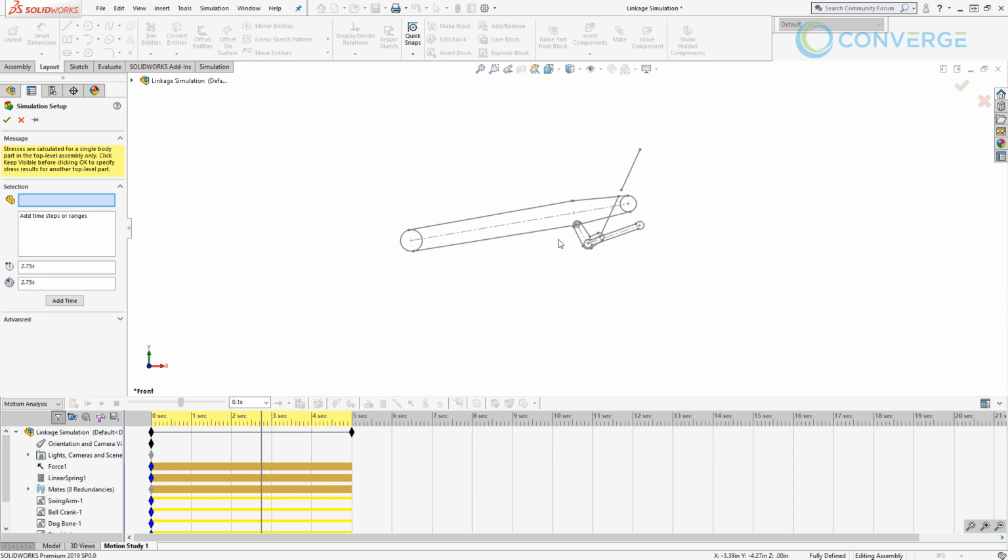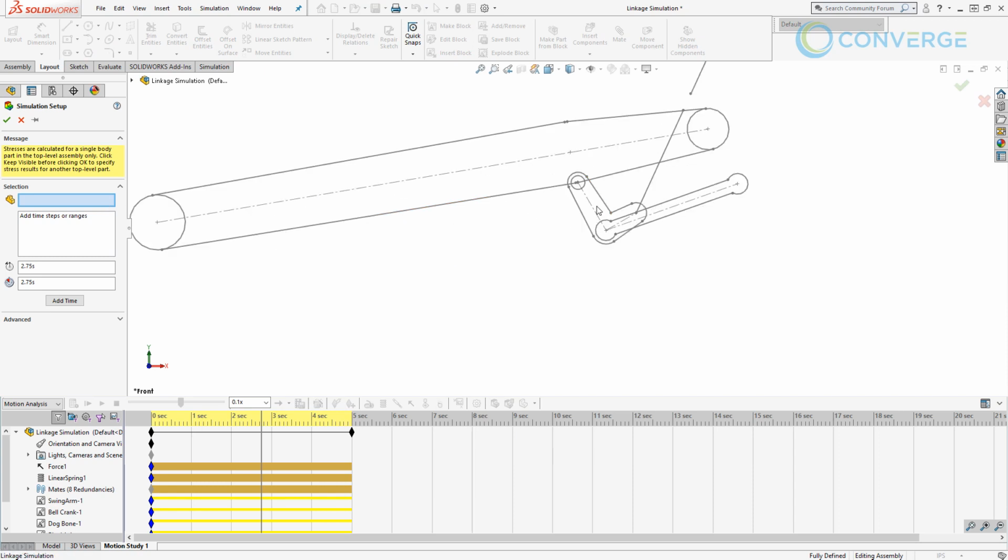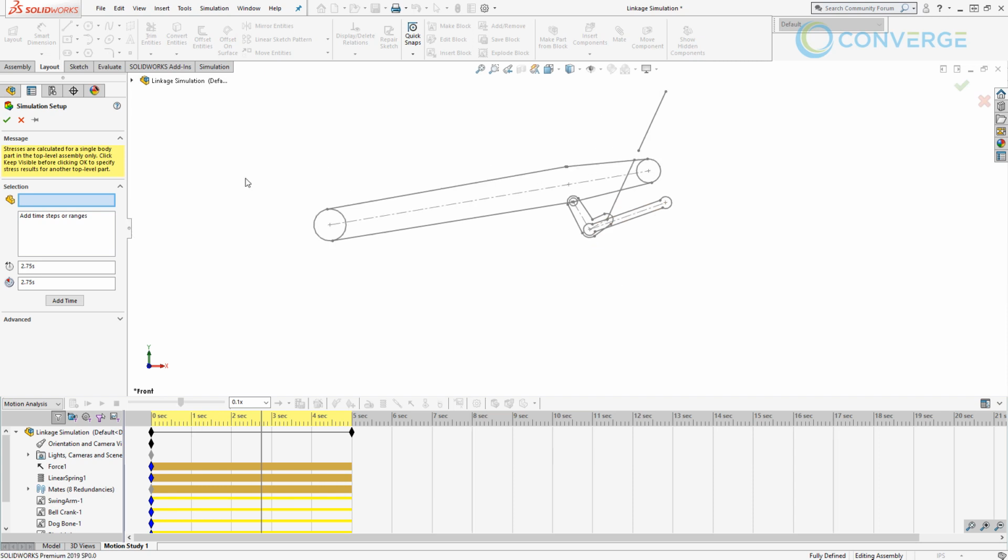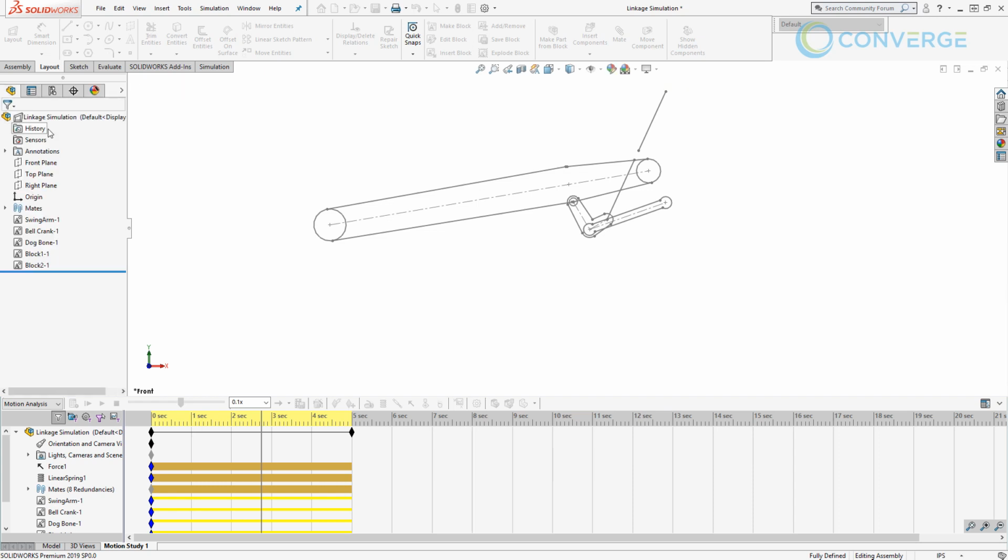We have to select the things that we're looking at, maybe potentially one of the sketch blocks or a specific point in time that we want to look at. Simulation run inside of a motion study can be extremely helpful. Now, while you can do some simulation with sketch blocks, and we can obviously do the kinematics we've already talked about, this isn't really going to be an option for us during a motion study with our sketch blocks.